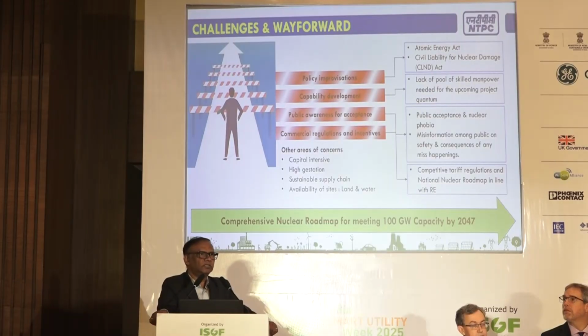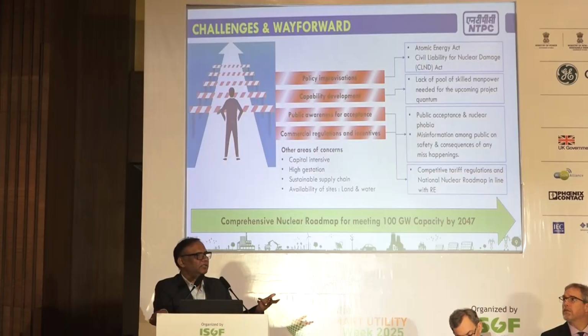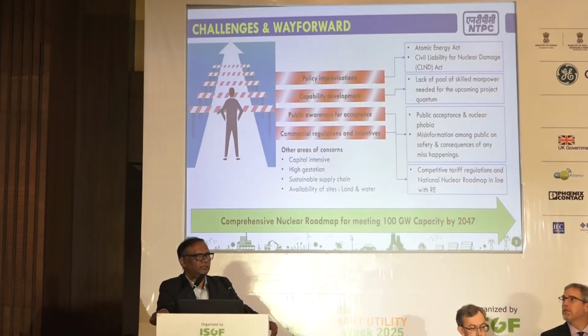So about double the amount of water which a thermal power plant needs, maybe 10 times the water a solar power plant needs. So for that, we are trying to adopt innovative technologies like dry cooling systems, adopting air-cooled condensers. Nowhere has it been adopted so far for a nuclear power plant, but we are trying to adopt it so that you reduce the dependence on fresh water. Getting land may be easier than getting water.